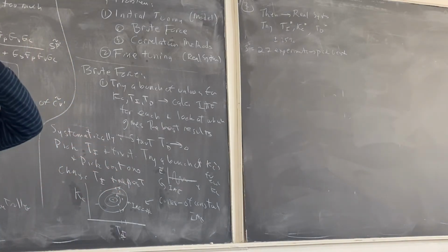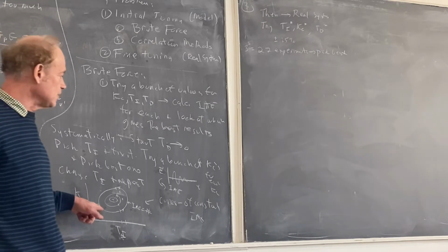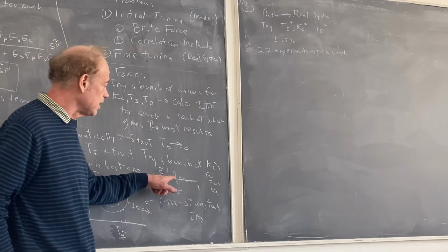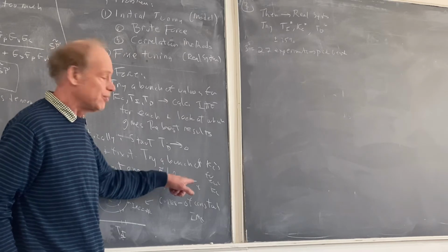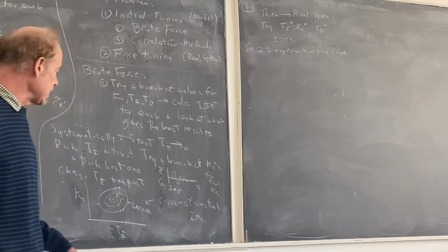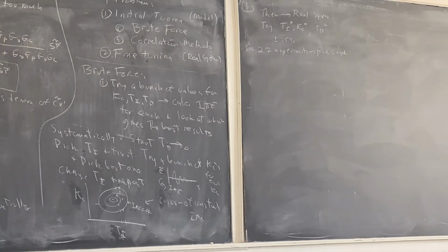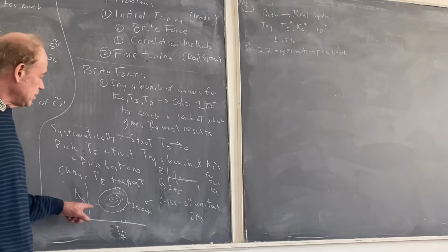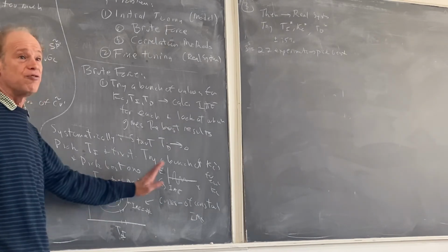Okay. So the area inside the ring represents the... We're not worried about areas, that's not something we calculate here. The area on this curve is not interesting. What's interesting here is the area under the absolute value of this curve. That's the IAE, and that gives you one point here. Okay, so these are contours. That is, for every value of KC, TI, I have a value of IAE.